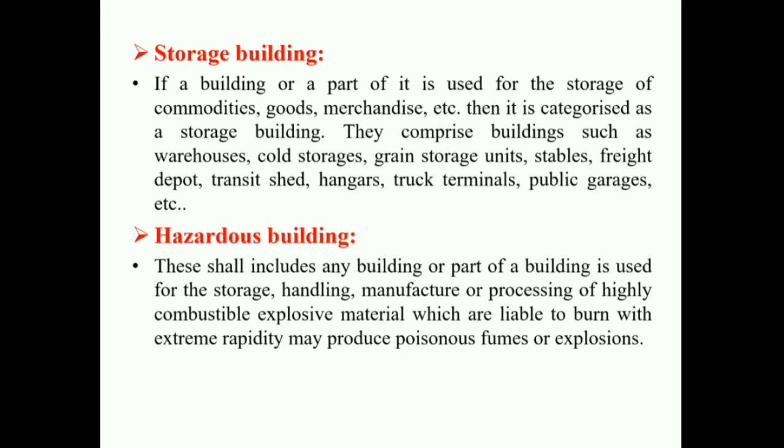Now last is a hazardous building. This includes any building or part of a building which is used for the storage, handling, manufacture or processing of highly combustible or explosive material or products which are liable to burn with extreme rapidity or which may produce poisonous fumes or explosions. It also includes buildings used for storage, handling, manufacturing or processing which involve highly corrosive, toxic alkalis, acids or other liquids or chemicals producing explosive reactions, etc.